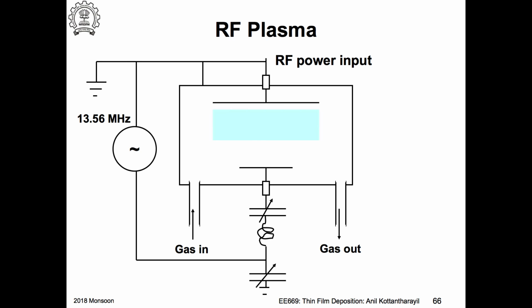So you may have oxygen, nitrogen, but not toxic gases, usually not very dangerous gases. But when I'm doing PECVD, I may actually pass silane, phosphine, and so on and so forth. So this whole thing will now have to handle corrosive and pyrophoric and toxic gases, very important.